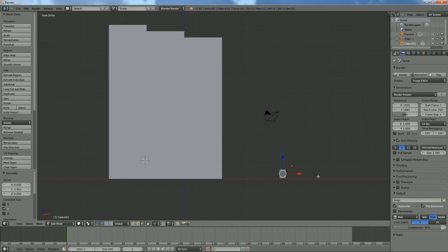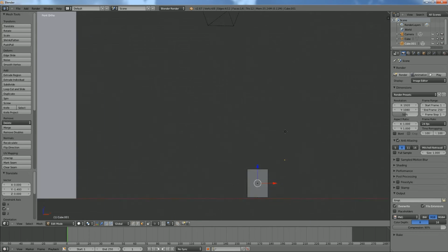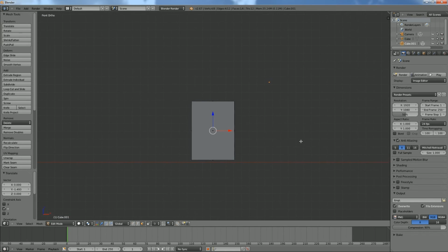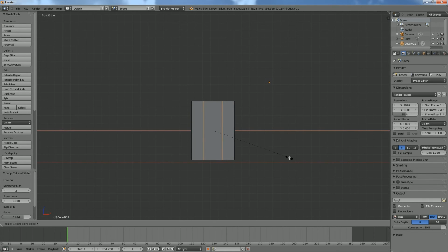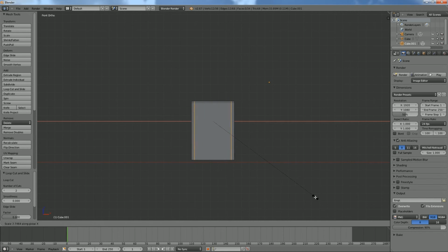So we'll go to front, and same thing we were doing the doors over here, we'll just set them up here. So we'll go Control R, and we'll scale these on the X, bring those out to about there, and Control R, move this to the top. And now we'll set up our door frame. So do Control R again, go to mouse wheel, scale that on the X.